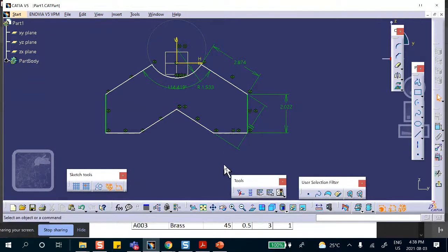I'm not going to say it's equal to W, but I'm saying this dimension is equal to that dimension, and of course this is going to be W eventually. That's one way. Or you can dimension it and say this dimension that you make is equal to W. That's entirely up to you. But the point is that you need to dimension this. Okay.